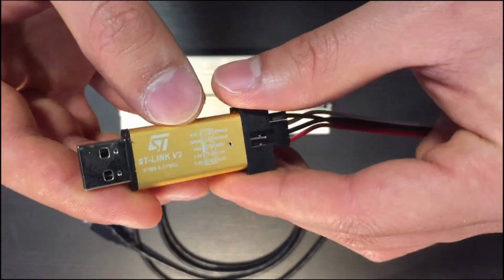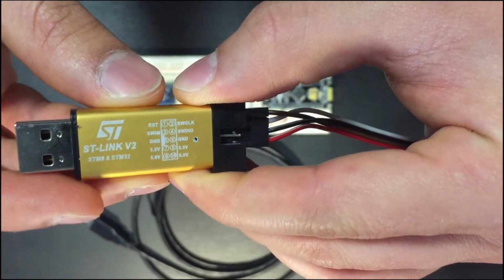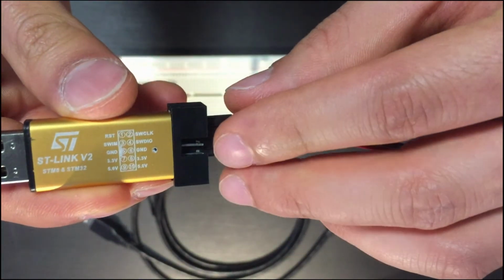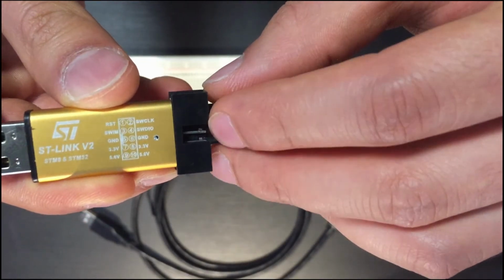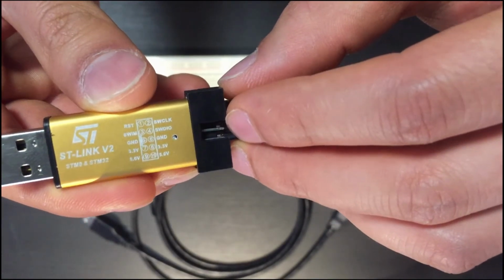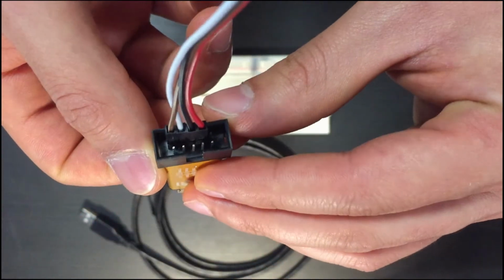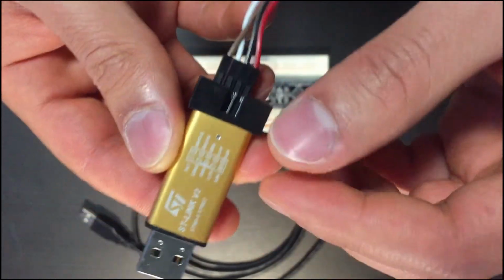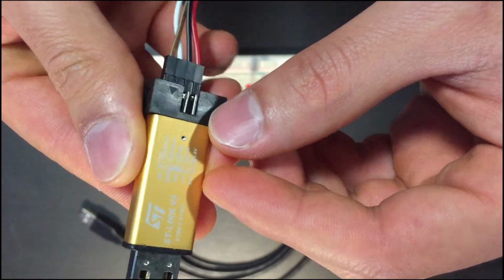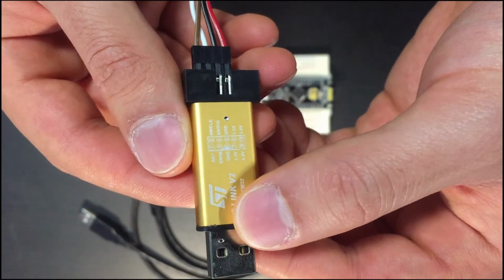Okay, how do we plug in the ST-Link? So here we see this white mark on the top that tells us the position of this socket. So this slot here shows us which pin is which. So the top left corner, if we flip it like this, the top left corner is pin 1. We're gonna plug in to pin 2, 4, 6 and 8. Here you can see it better, guys.